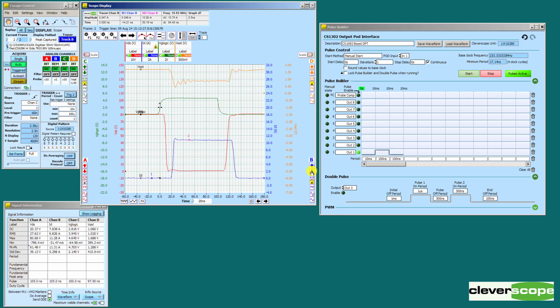I'll just move this down a tad. So here you can see the voltage, and it's around 80 volts. The current is around 10.7 amps. We're only using 80 volts to excite it. We are using a 7.33 ohm load resistor with 80 volts. You can do the maths. It's around 10.7 amps.